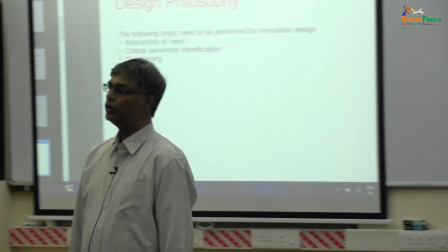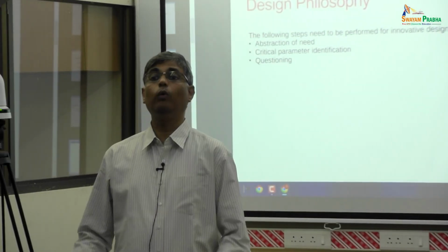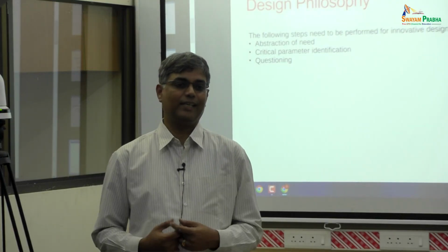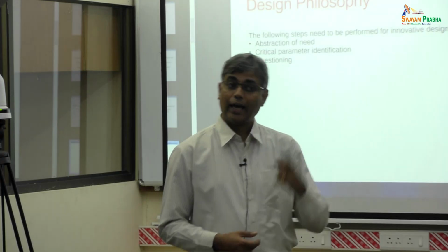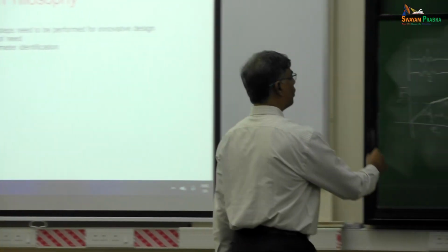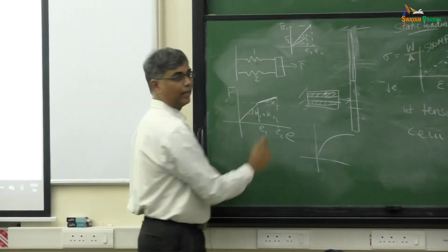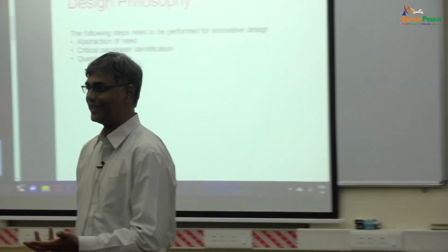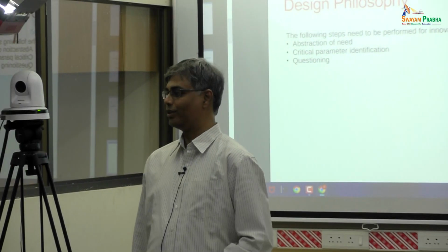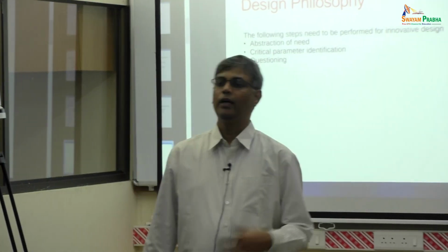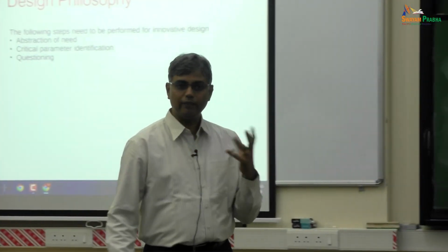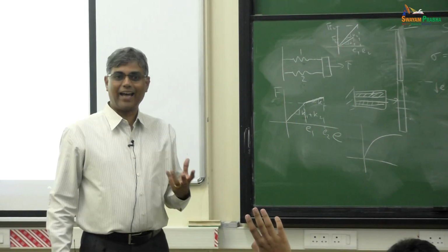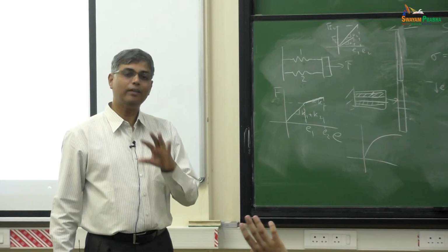That means there is a certain amount of inelasticity, so it's no longer an elastic curve. Elasticity means you follow the same curve in loading and unloading, whereas here there is some permanent damage that has occurred, and therefore it follows a different curve. So this is a very simplistic model. There might be some aspects that will not be exactly what you would expect in real life, but that's okay.